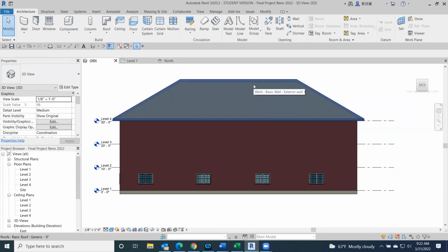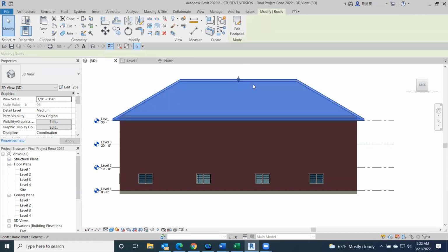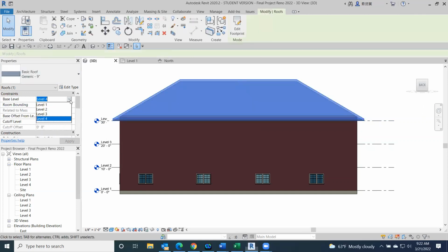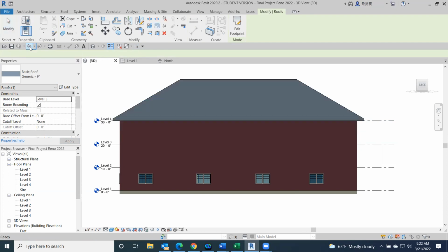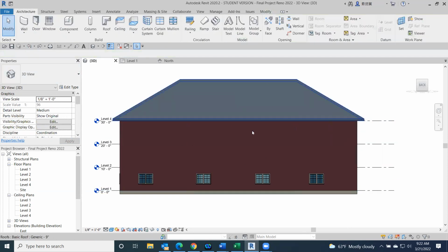So if we even wanted this just to be like a 2-story, we could just change the elevation to this to level 3. Obviously, the walls will move at the same time. The soffit is independent of that, but we can change that later. But it's very easy to manipulate that. So it's real easy to create a bigger building just by doing these little things here.